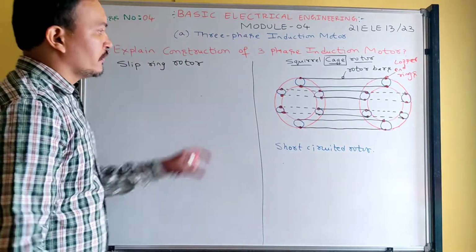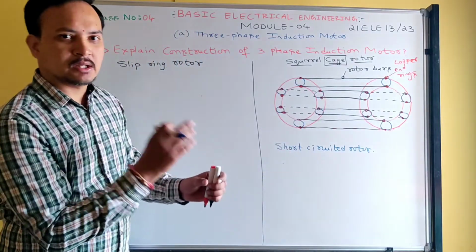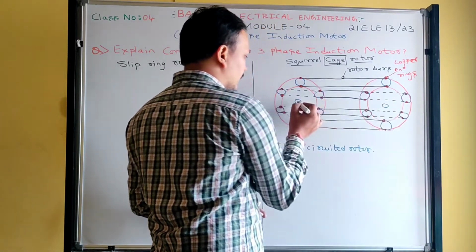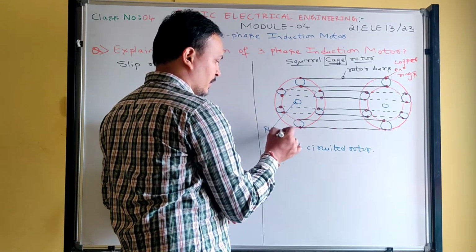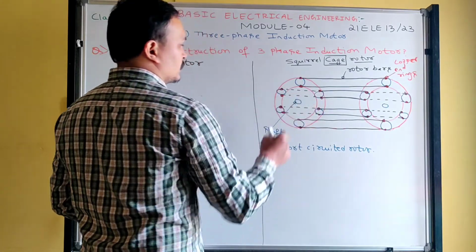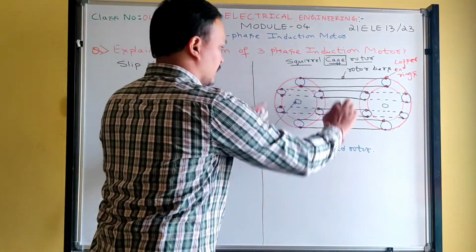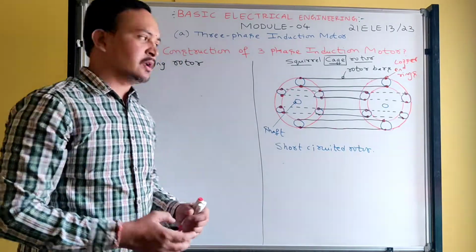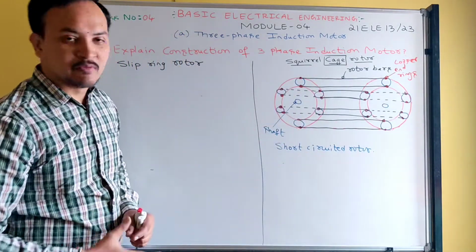Okay. So assume like this rotor, this ready-made rotor I am putting inside the stator, and finally this rotor is mounted on the shaft. This center circle that I wrote is called the shaft. That is not a rotor bar or rotor hole, that is the shaft. Once I place this rotor inside the stator, the outer part will be the stator. Give supply to the stator, it carries current, produces a rotating magnetic field, and that magnetic field is cut by the rotor bars, rotor conductors, and then EMF will be induced.